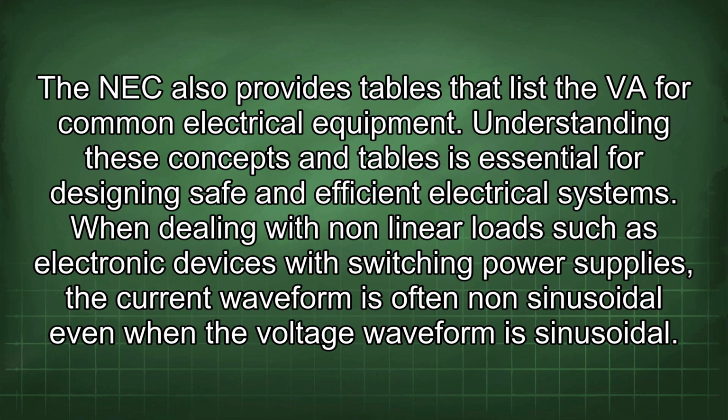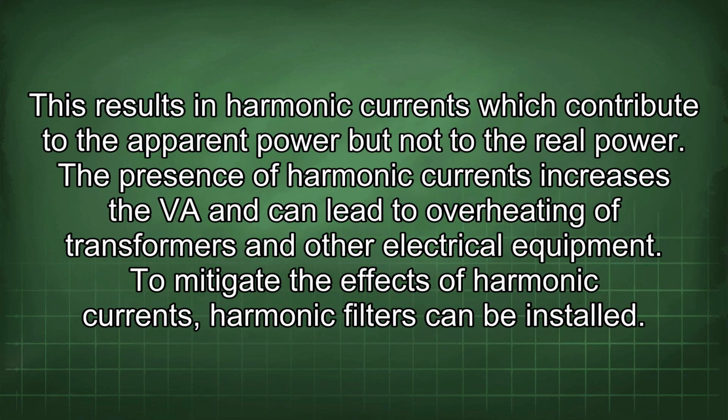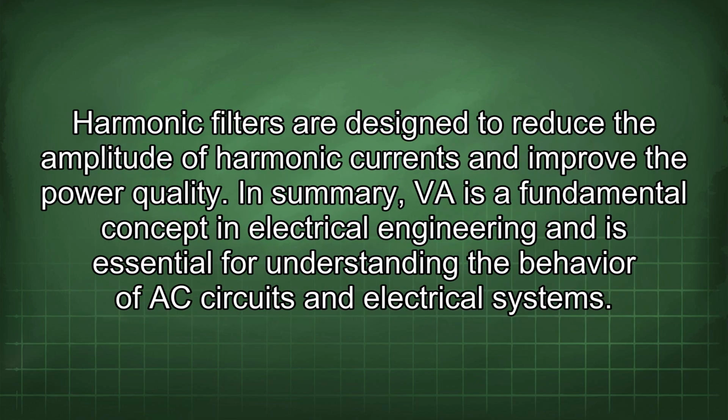When dealing with nonlinear loads such as electronic devices with switching power supplies, the current waveform is often non-sinusoidal even when the voltage waveform is sinusoidal. This results in harmonic currents, which contribute to the apparent power but not to the real power. The presence of harmonic currents increases the VA and can lead to overheating of transformers and other electrical equipment. To mitigate the effects of harmonic currents, harmonic filters can be installed. Harmonic filters are designed to reduce the amplitude of harmonic currents and improve the power quality.